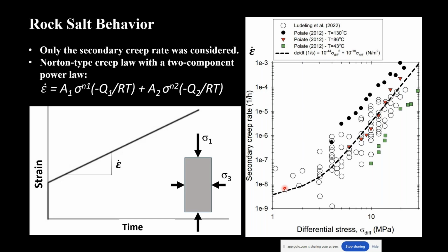When we are increasing the differential stresses, we are approximating the grains to each other, and then the adsorbed water starts to dissolve the salt grains, and this is a very slow creep mechanism because of that. There are several creep mechanisms, but those are basically the more important, right? And that's why we have two components, and we are just summing these components.